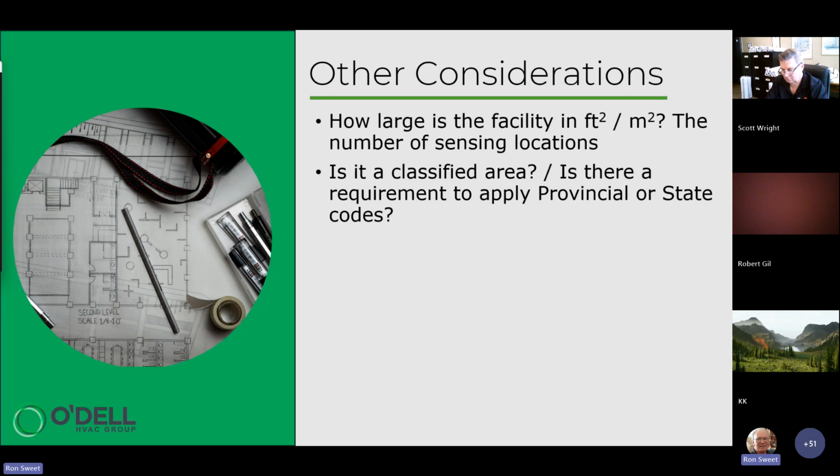An explosion-proof device, on the other hand, is designed such that the electronics or electrical parts are encased in an explosion-proof housing, such that that source of ignition is encased, so that if any combustible gas seeps in or leaks in to come into contact with that electronics, which of course could be a source of ignition, then that housing will contain that explosion.